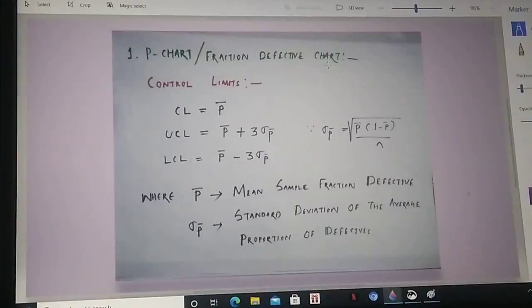So I want to remind you one thing, that control chart for the attributes. What does it mean actually? Because control charts for the attributes are used to achieve and maintain an acceptable quality level for a process whose product cannot be subjected to quantitative measurement but can be classified as good or bad, acceptable or non-acceptable, defective or non-defective, percentage of defective, etc. So basing on that, four types of charts we have. So P chart, it signifies the fraction defective